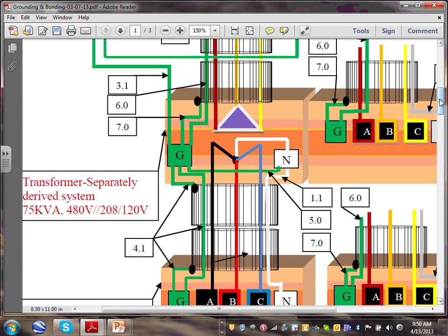Separated drive system. Now we finished at least 4 chapters based on what we did now. Separated drive systems. So really the grounding and bonding, guys, every one of these has its own unique characteristics. So we ground and bond at the service. You saw how we did that. Or ground and bond at a sub-panel in the same building and another sub-panel in a different building.